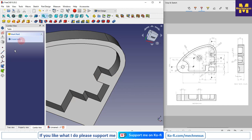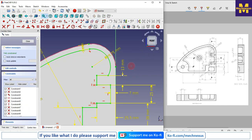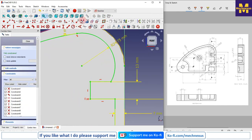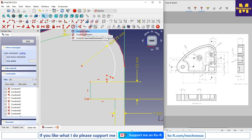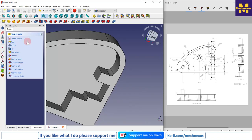So to fix this, we will go to our sketch and provide the fillet in the sketch. So I will select the fillet and select these 2 points, and here I will give the radius 5. Now I will close it.